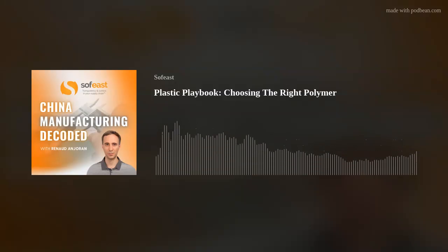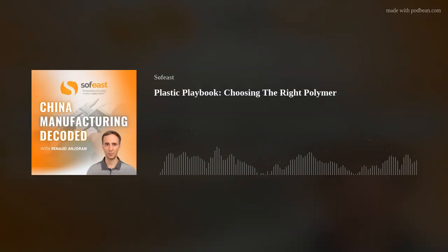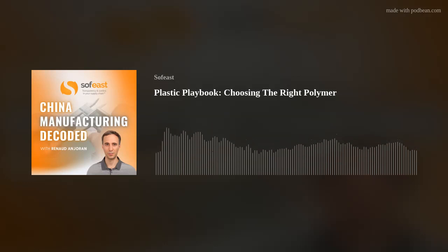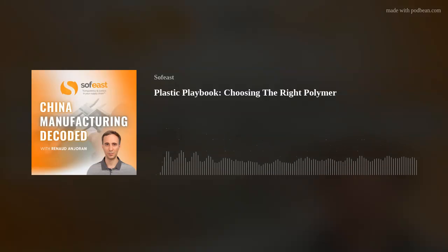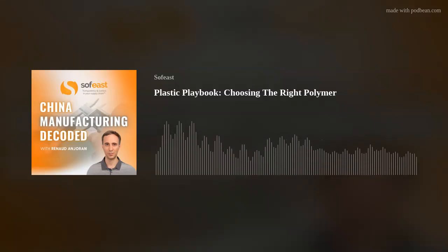Now, again, it's going to take on some of those properties from the ABS. In other words, it's got good impact strength. The heat resistance does improve because PC has very good heat resistance properties as well. So we've got the surface finish is very good. Again, looking at some of the limitations, it's not as good as PC on its own or ABS on its own, but it's a very, very good, improved overall property set from the ABS.